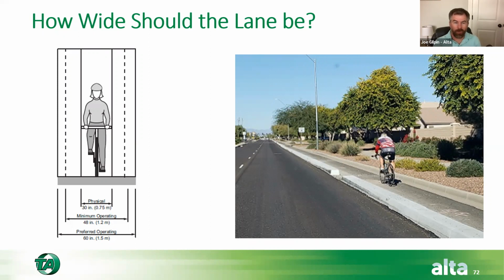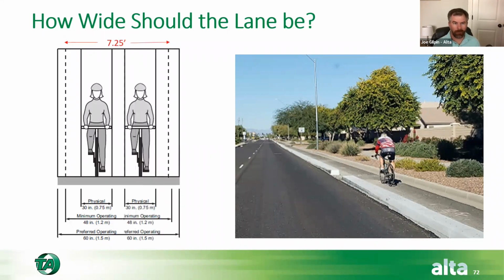But there is a way to work with those folks and get them to really enjoy and promote the project, and that becomes the type of width that we're looking at. Again, are we designing to that single bicyclist, or are we designing to that side-by-side passing? Do we have the width to be able to enable that? If we do, I found that resistance tends to lower from those experienced, very vocal bicyclists that you may have seen in some cases resist a facility that might really create conditions for a lot more people to enjoy bicycling throughout the community, which is unfortunate.